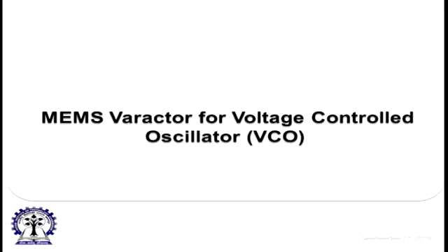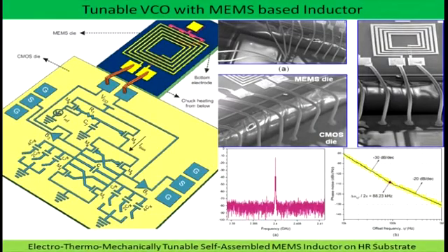So can you think of a new technology itself, a quantum jump, a new breakthrough? Then we thought, let's make an inductor lying on top of the 6th or 7th metal layer, depending upon the process, and then make it hanging. If you hang it, you can reduce the eddy current loss, so you can improve this quality factor. That's the structure. What we have done, you can see yourself. This is the hanging inductor, this is the 130 nanometer CMOS circuit, and this is connected through bond wires.